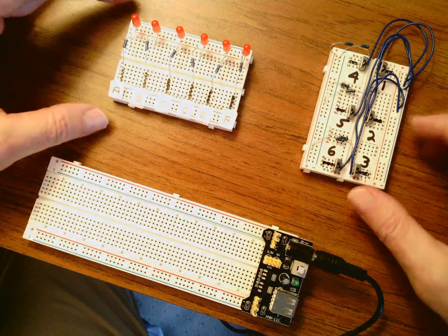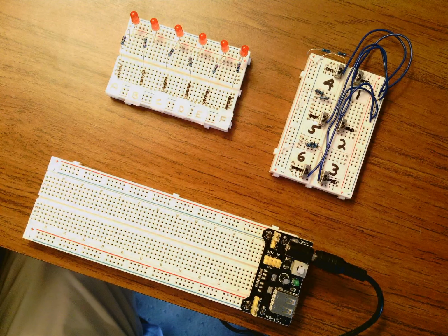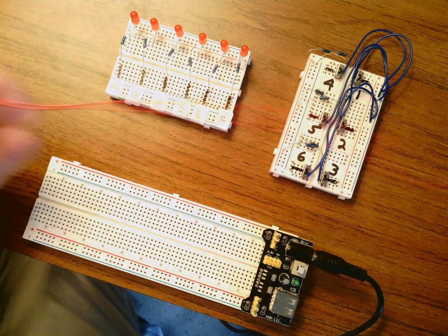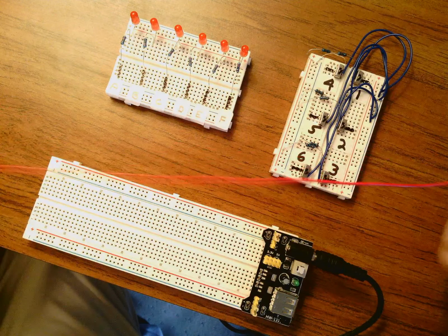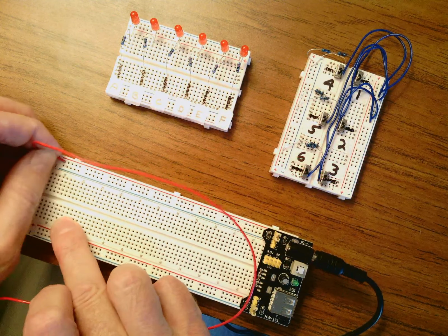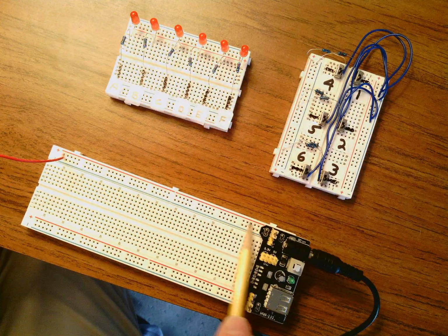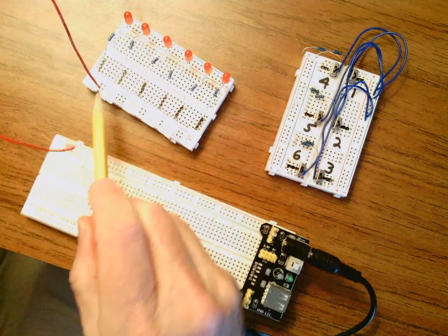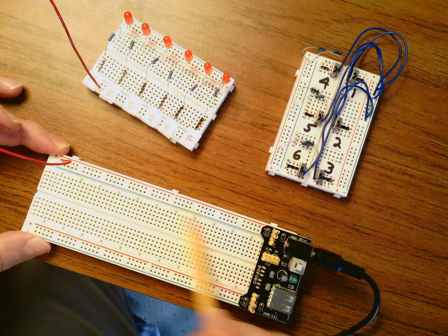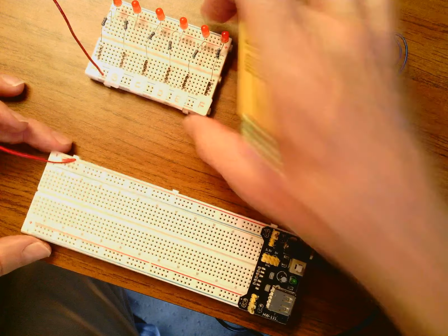So the first thing we're going to do is electrically get these boards connected together. I'm giving you 4 pieces of red 15-inch wire. You're going to take one and connect the 5-volt rail right there. Now this power supply puts 5 volts on this top rail when it's turned on, and I need to get that over here. Be careful. It has to go to the red rail over here, which is this point right here. So I just tied VCC, or plus 5 volts, from this rail to that rail. So these are connected electrically with plus 5 volts, which we call VCC.